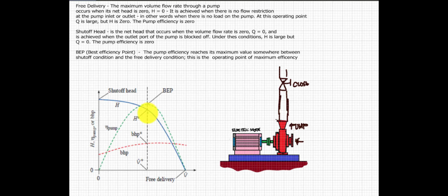You can save money at this point of selection. So don't forget, when you are selecting the pump, please always refer to the best efficiency point.